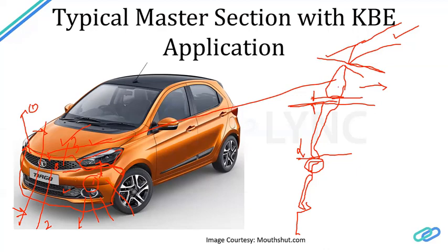And then this chrome strip is developed, and this will have another flange which I'll be using to create the lower grill and the bumper skin. This is all about the parting lines and the flanges used to create each other part.